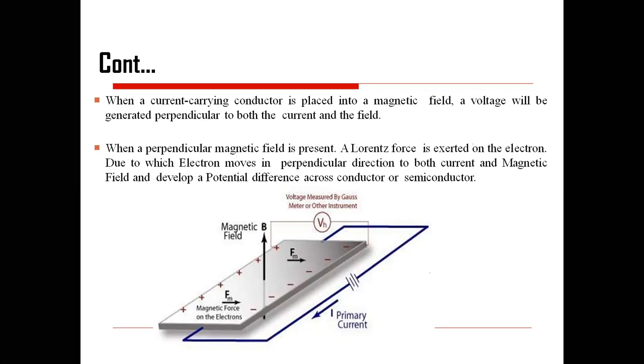If you observe, one is a blue line, where an external power source has been applied to a plate. The reddish part is the voltage which is supposed to be measured, and the black line B is the perpendicular magnetic field which is generated. This is possible when we apply the external magnetic field perpendicular to it, and only in proportion to that will your voltage be generated.